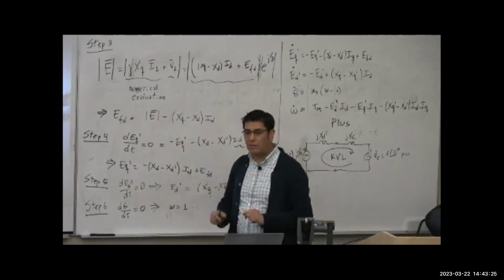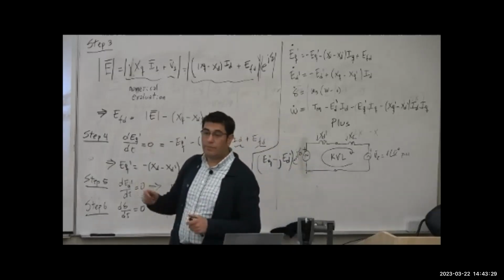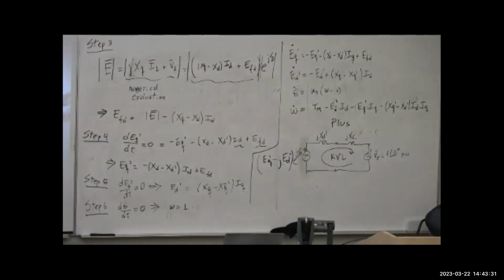You know the magnitude and you know the angle. It's just a circuit. From here, you determine the voltage and the current at bus 1. In the model, you know this current, you know this voltage, you know this impedance. So this voltage plus the voltage drop in the impedance will give you E phasor. So that's completely determined.